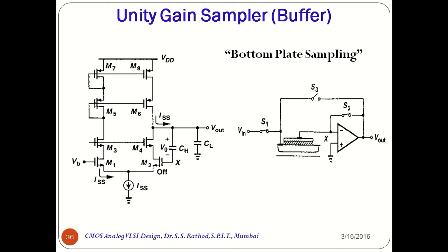This technique is called bottom plate sampling. Basically, driving the bottom plate by the input, or the output, avoids the injection of substrate noise to node X.